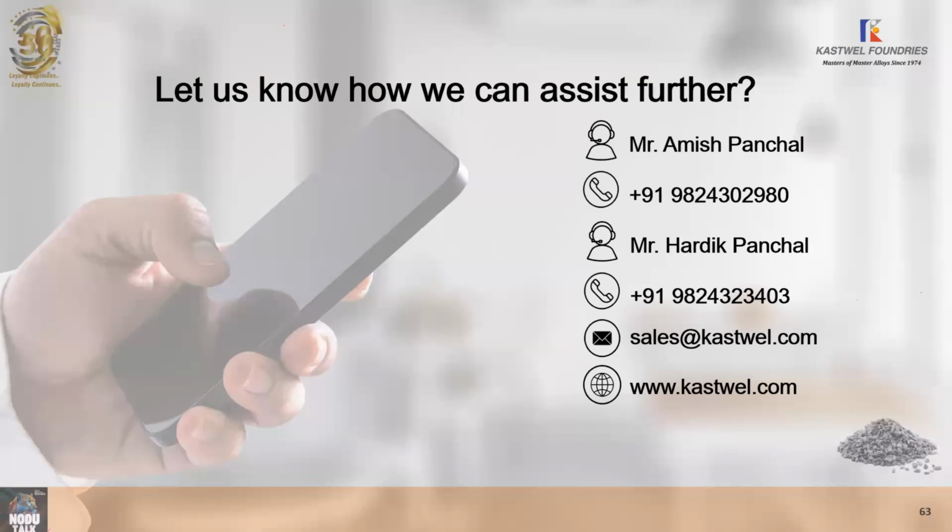Because when I'm pouring from the riser ingate from the inside of the core of the casting, it remains hot for a prolonged period to feed the casting, because on the outer thickness we cannot place the ingates or risers. So how much in that case should I look at core quality or core ingredients? Because I think sulfur or oxidation can also be picked up from the core.